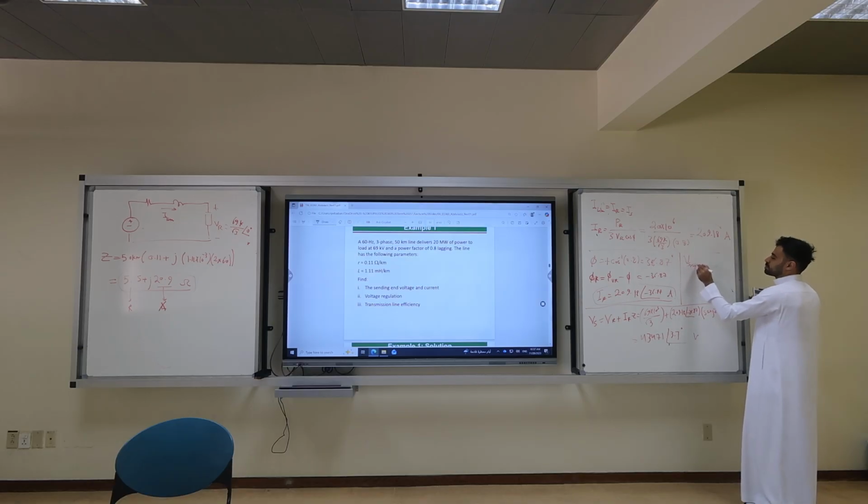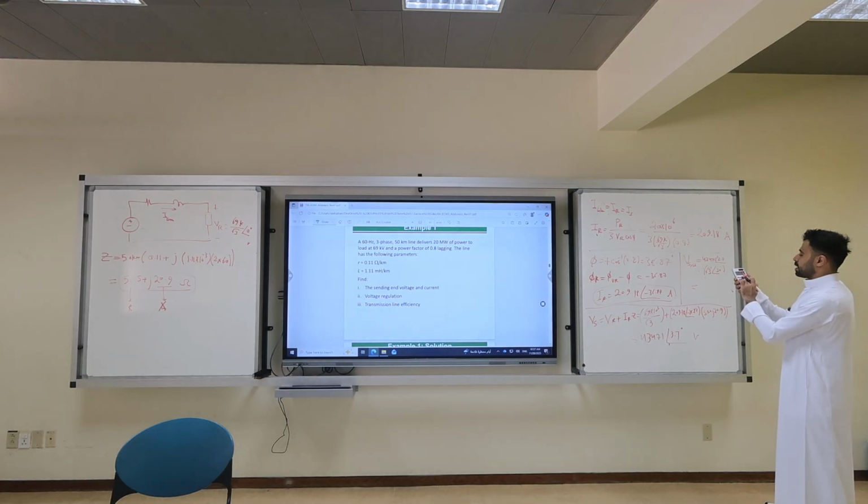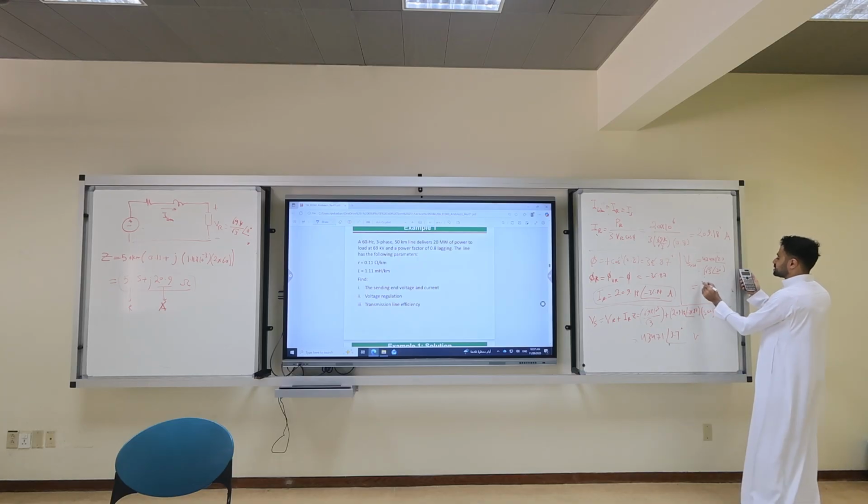So what is VS line to line? It is 43471 angle 3.7 times square root of 3 angle 30. You agree with me? So the answer is 75.294 angle 33.7 kilovolts.